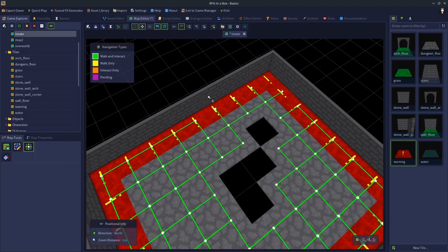Because if I start drawing from here, notice how the pulsating dot has changed. See how if I hover here, it's growing and shrinking. If I hover over here, it's not. It's doing the faint glow. So if I click and hold from here and start dragging, it's drawing it on the wall, right? My mouse is over the wall, so as I drag these lines, that's where it's putting them.